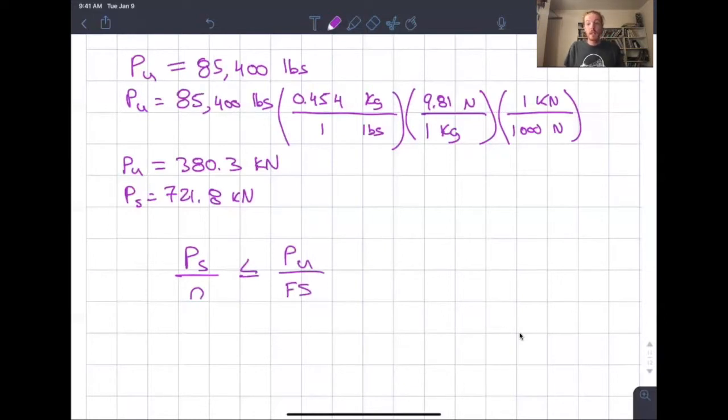So this assumption where it gets divided evenly over all the cables is a simplification. Typically, you'd want to separate it out by stiffness, which we'll get into in the advanced design course. But for now, we're going to use this relationship to calculate the number of cables, but know that there is a more precise way of doing it using the method of stiffness for developing your load path. So I want to make that note.